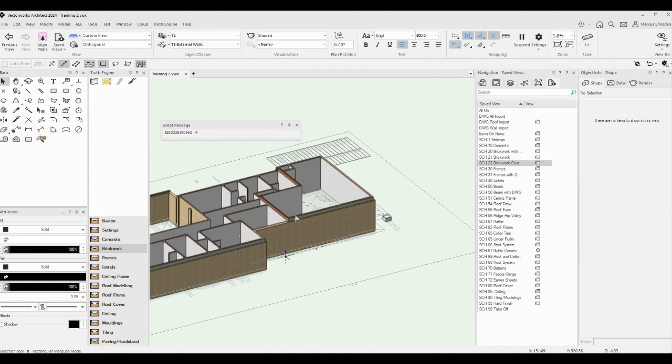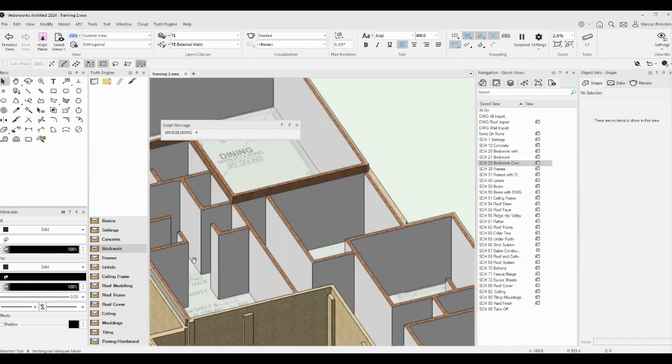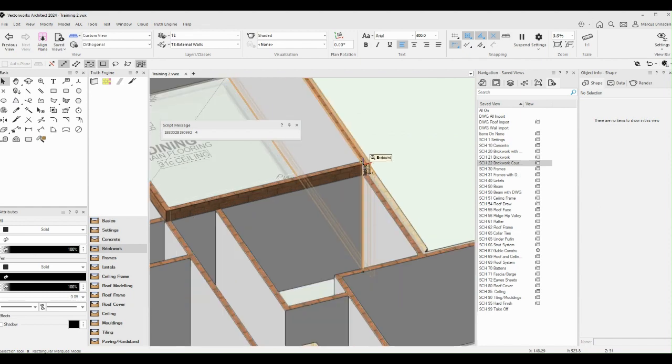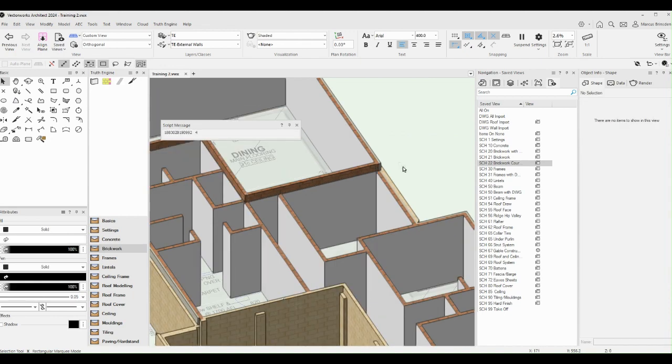And looking at that, that raises the question of how you would actually finish that off. It might be a stud wall to get your starting point for your rafters, but I'll leave it like that because you could also bring that internal leaf up 3 courses, then turn the plaster off. Interesting to see how that is actually built.